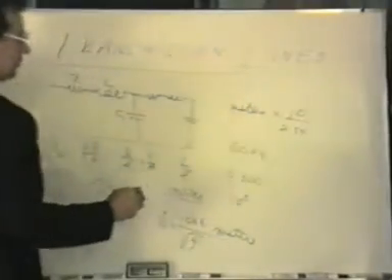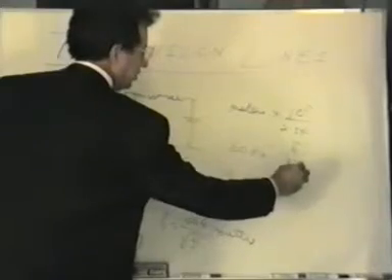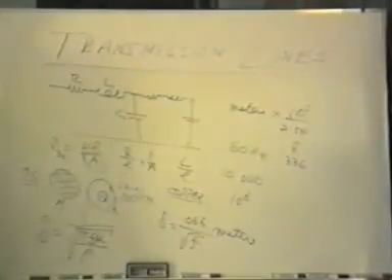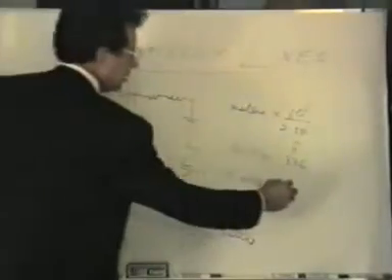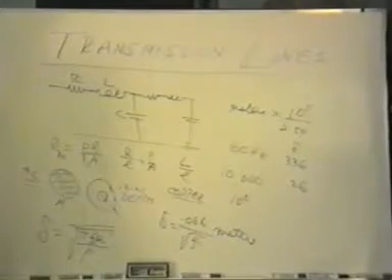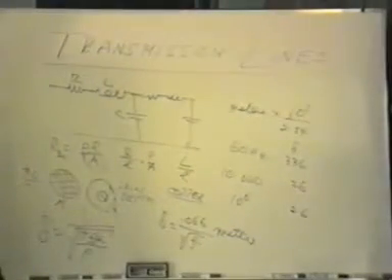Here are some of the values you will find for skin depth. Delta up here is about 336 mils. At 10 kilohertz, it drops to about 26 mils for the skin depth. And at a megahertz, it's about 2.6.